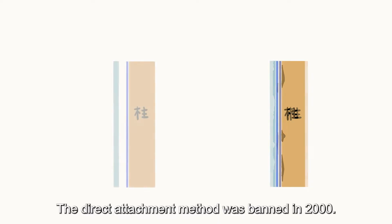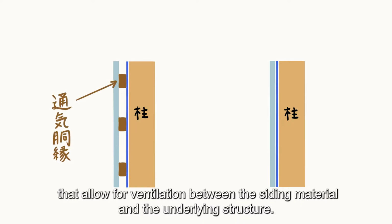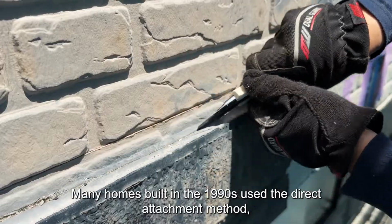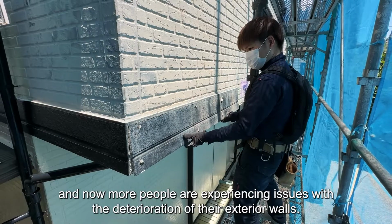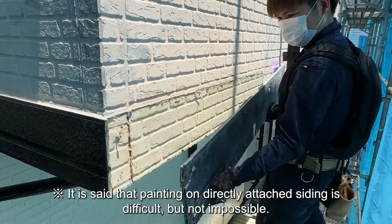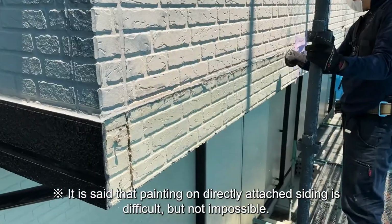The direct attachment method was banned in 2000. In modern new homes, it's necessary to use construction methods that allow for ventilation between the siding material and the underlying structure. Many homes built in the 1990s used the direct attachment method. And now more people are experiencing issues with the deterioration of their exterior walls. It is said that painting on directly attached siding is difficult, but not impossible.